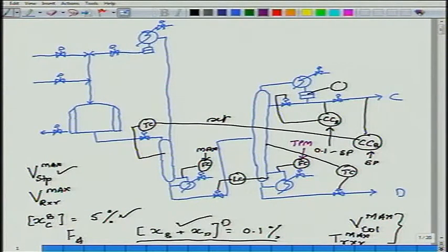So, I have a certain desired value of fresh A processing rate. I will adjust my throughput manipulator set point such that the amount of fresh A that is getting processed is what I desire. So, this is also taken care of.